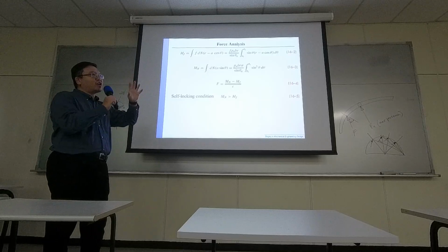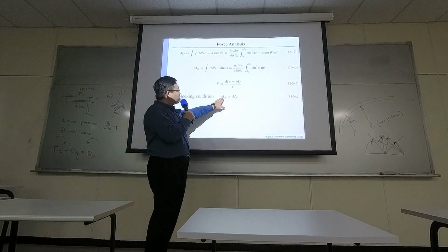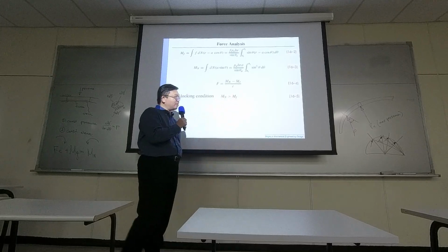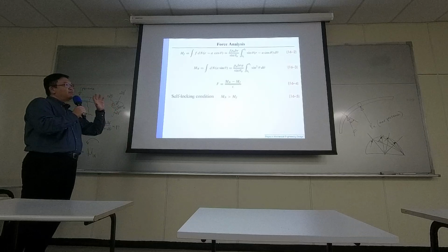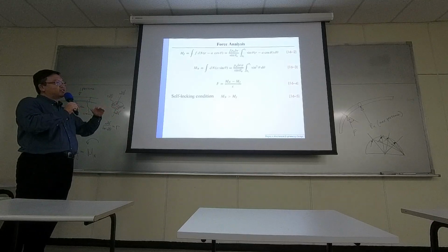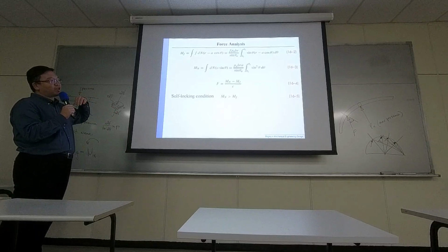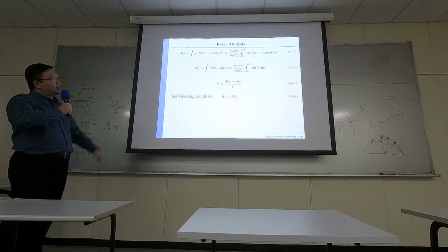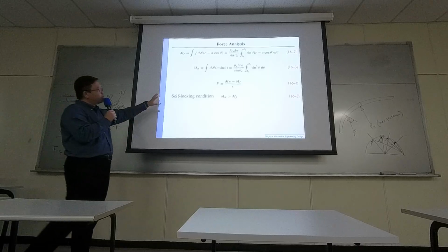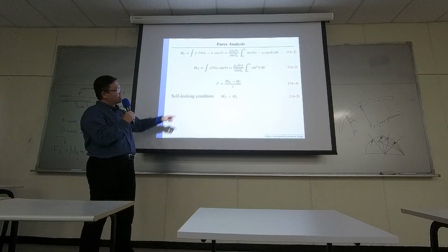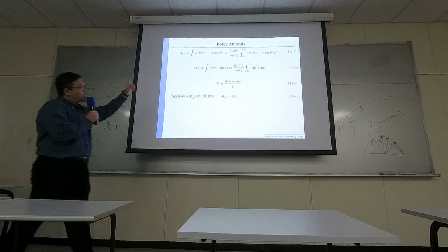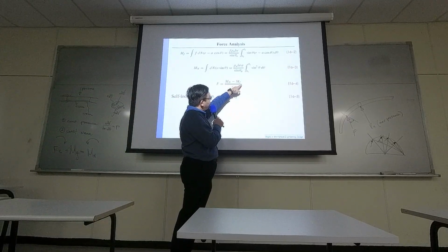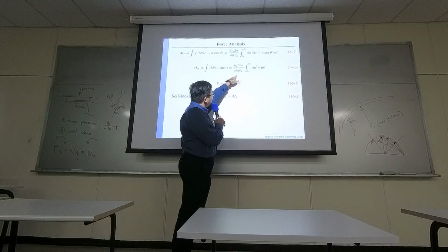Depending on different geometry, the moments contributed by the normal force and the moment contributed by the friction force may have different amplitude. You really need to do some calculation to figure it out. And there will be a situation where you will have so-called self-locking. You have a positive value right here.